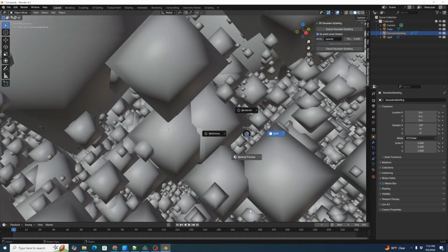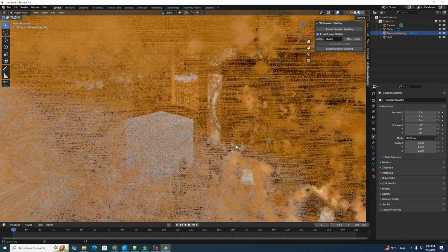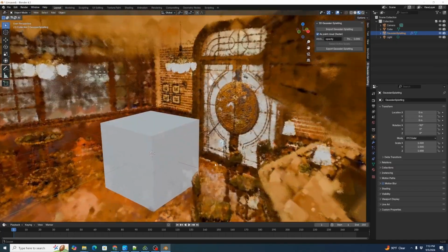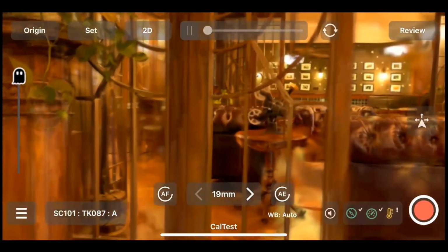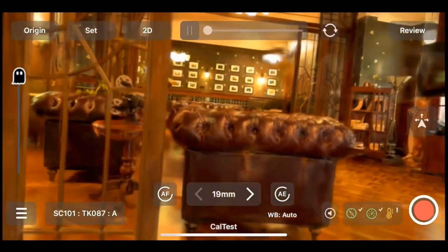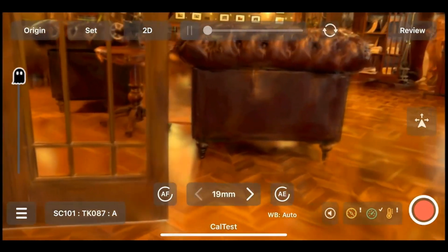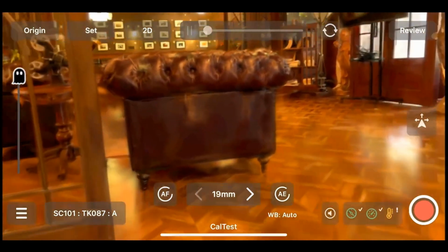We are going to work through our new Gaussian Splat authoring workflow to construct composite models that can include both USDZ 3D information and Gaussian Splat information. And this will let us do a lot of neat things. Gaussian Splats by themselves have some fantastic properties, but they don't inherently contain scale or orientation information. So if you want to use them in the real world, you need to provide them with scale and reference, and that's what we're going to do in this.